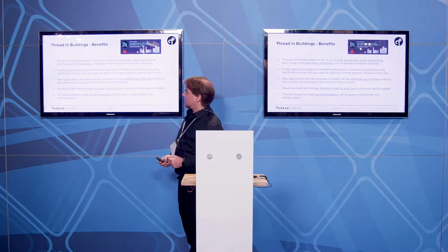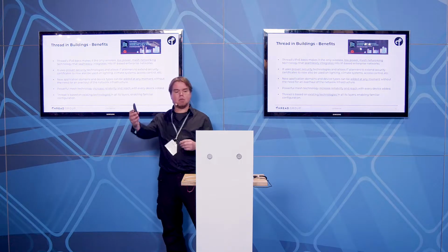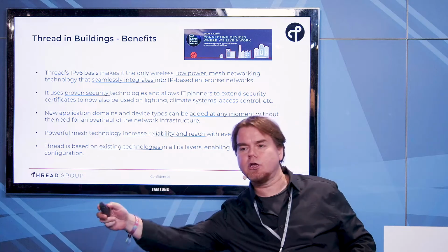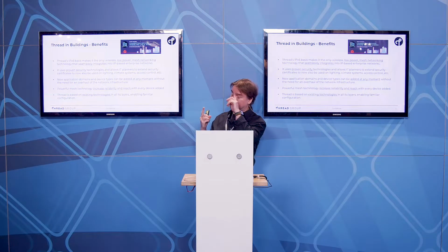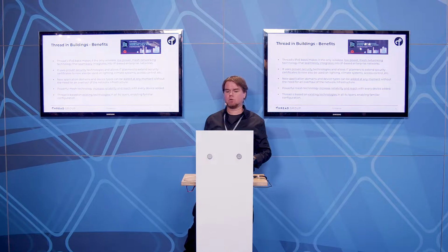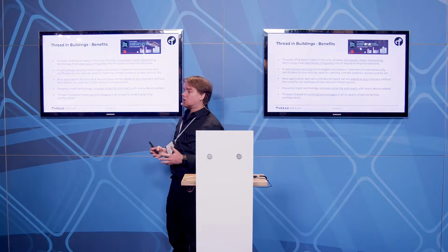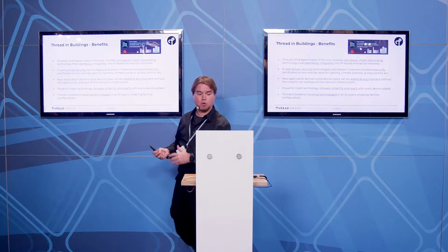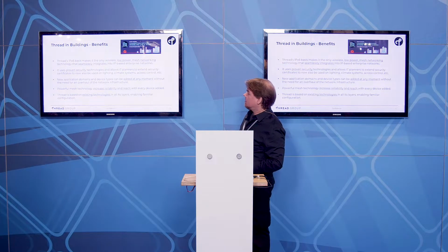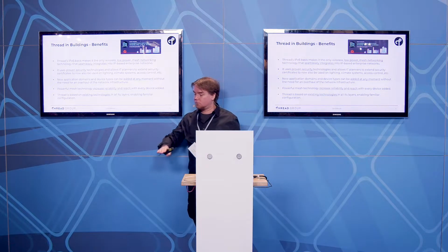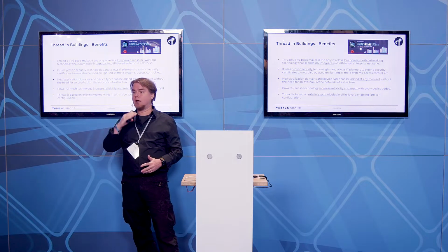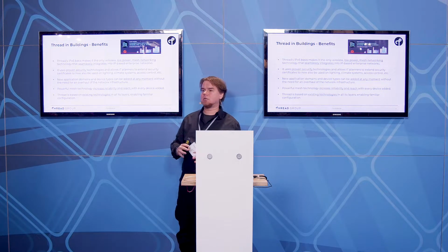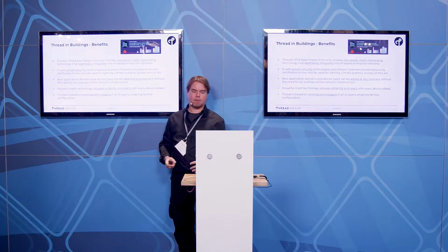Thread is a mesh technology. And mesh technology means that the nodes on the network extend each other. So the traffic goes from one device on the network to another device. So there's not one single point that emits the radio waves of the network, like in Wi-Fi, for example. And that means that the more nodes you add to the network, the more devices you have, the stronger the network becomes and performance goes up. And Thread is based on existing technologies. So from the 15.4 radio technology towards the IP technologies, security and routing, transmission control, and the applications, all of those things are existing things which Thread brings together into one proposition.